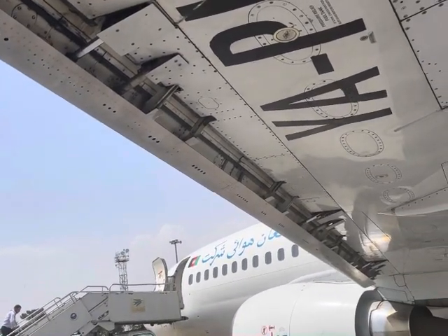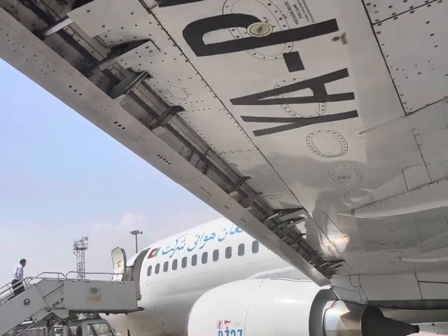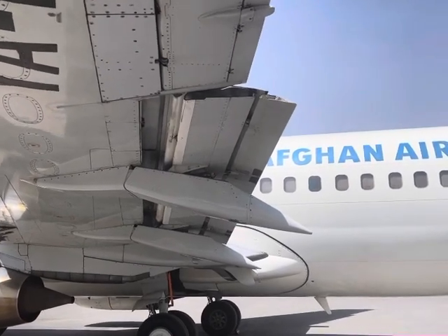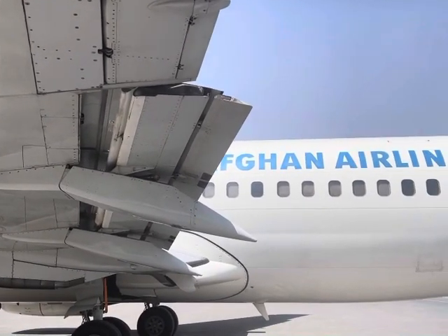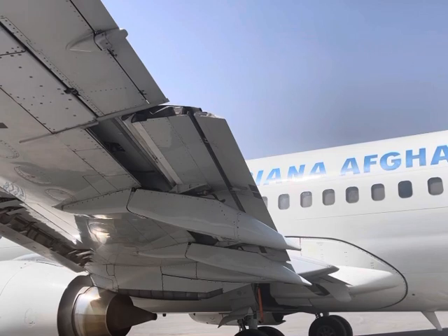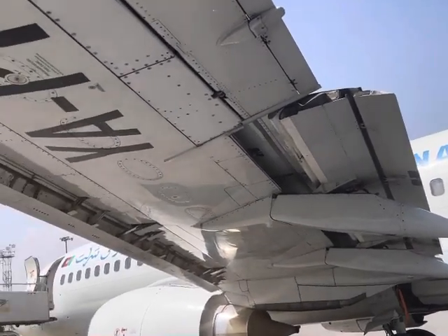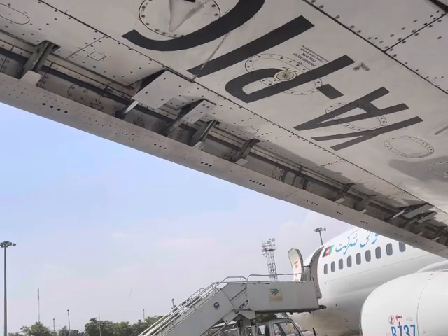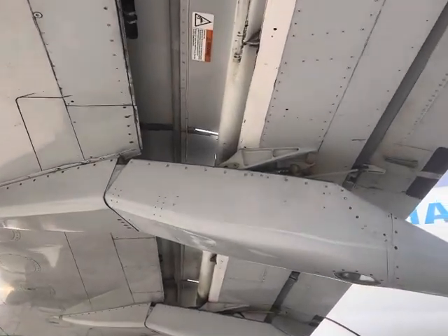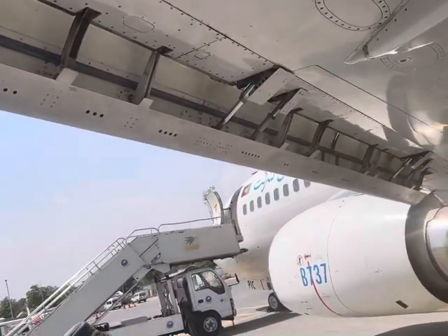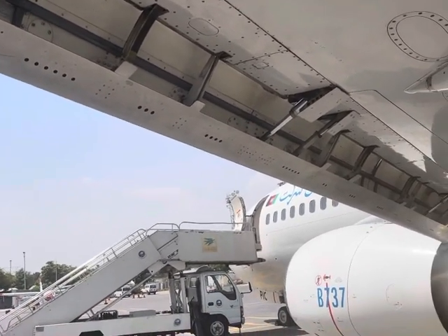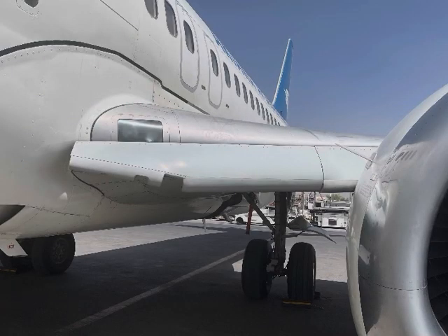Increasing the curvature of the wing helps it generate more lift, but besides generating more lift, increasing the curvature will produce another problem. The air which flows over the upper surface of the wing, due to more curvature, will not be able to flow smoothly on the upper surface, and some eddies, some currents, will be generated. These eddies or currents on the upper surface of the wing will increase the drag, and we should control this. Later we will see how we are controlling this.